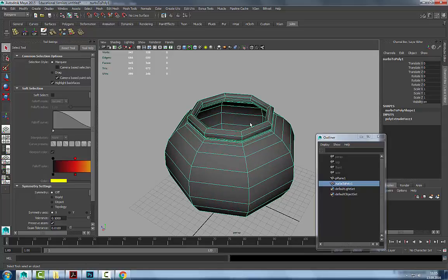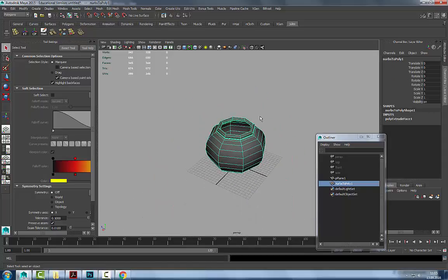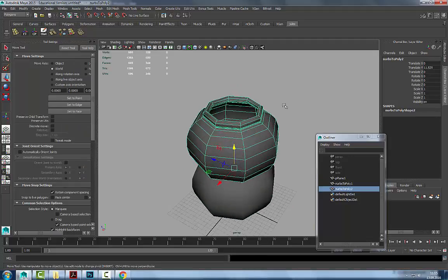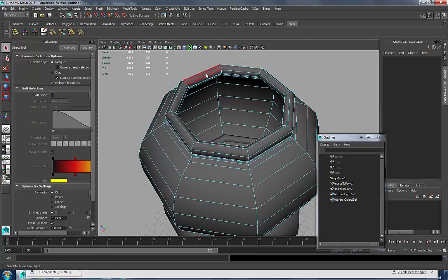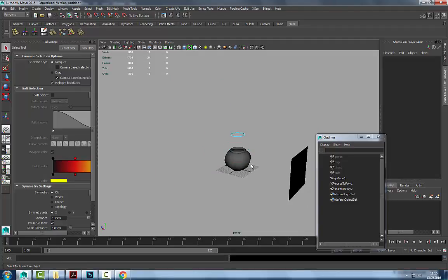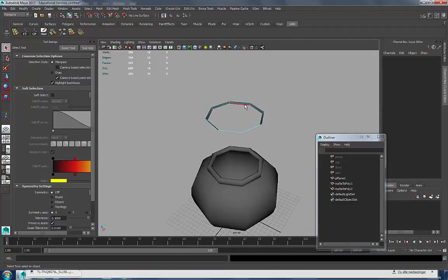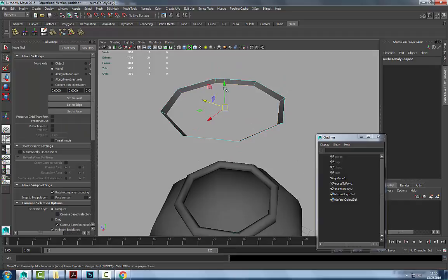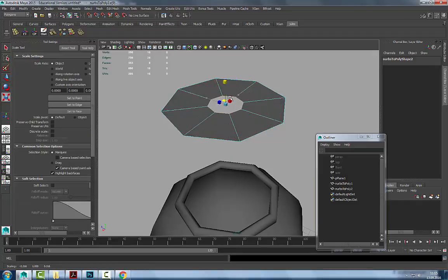Quickly, let me create a lid, because I want to make this point, that you can sometimes just use the existing object. So if I make a copy of this, because we already have this shape here, I can just select that shape, then snap this interior edge to these verts, and then scale them in.